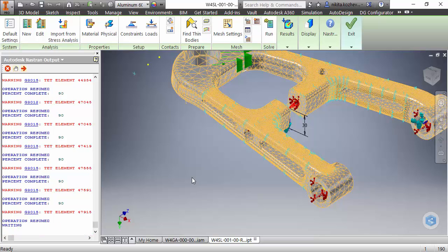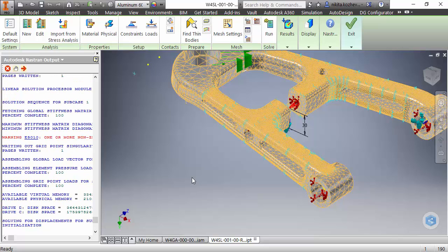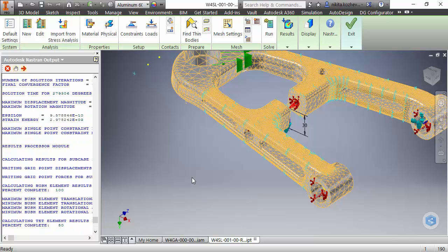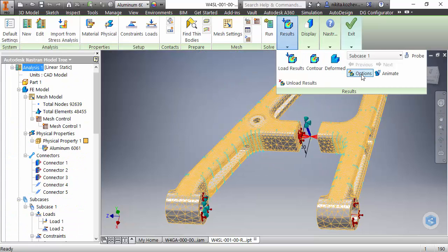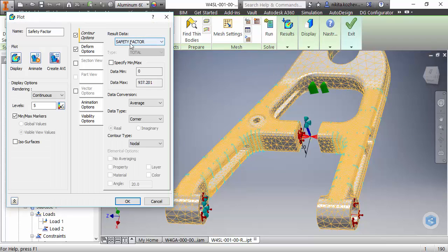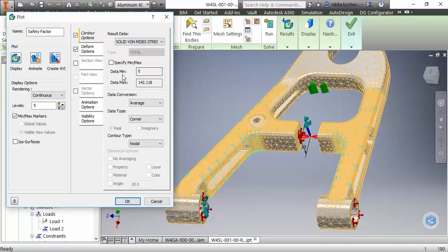By the way, Nastran originally came from aerospace industry, and has got a very good and proven solver. As I mentioned before, we are now doing the mesh convergence study, and therefore we need to compare results from the previous simulation with the new results with more accurate and fine mesh.